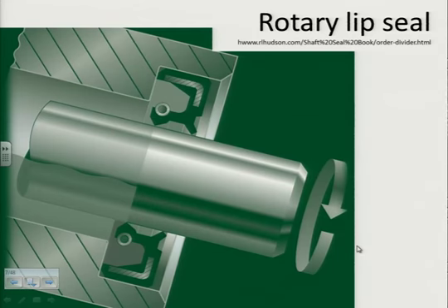Here's the fluid on this side. Let's do a nice blue fluid. There's the fluid, you can see there. Here is the lip seal, which goes all around the shaft. And the important part, which I'll do in red here, is this zone that is rubbing on the lip seal. Historically, lip seals were things like leather. Now they're polyurethane kinds of things. It's rubbing on the shaft, so we have this polyurethane material rubbing on what is very often a steel shaft.